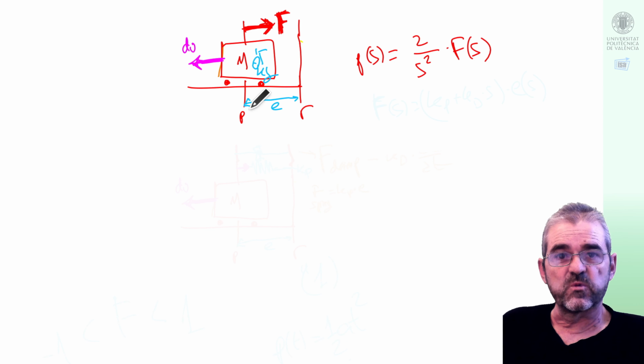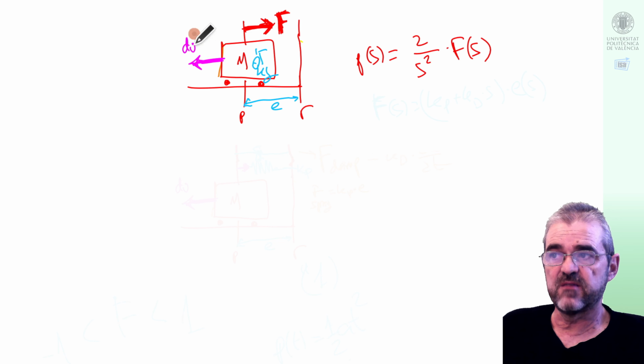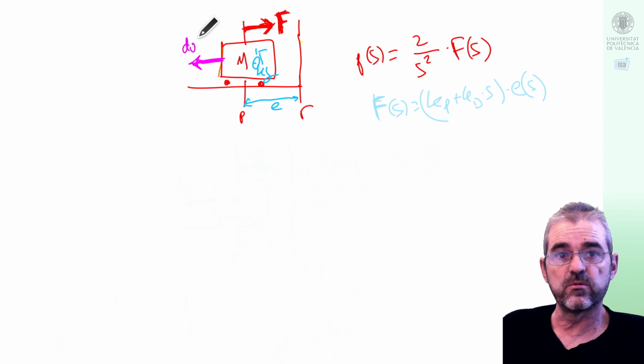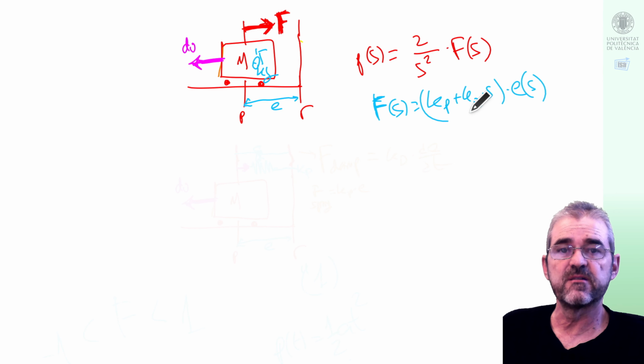Our problem setup was being able to move from a particular point 1 meter to the right. The difference between the actual position and the desired set point R reference is the closed loop error. And apart from set point tracking, we wished to somehow reject input disturbances, some other forces caused by wind or by, let's say, non-horizontal tilting of the platform in which my mass is moving. And well, we decided to apply a proportional derivative controller which had this expression here.